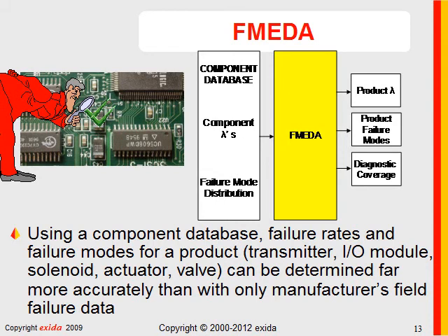But if, for example, that capacitor failed short circuit, it would take out a power supply, probably take a current on a 2-wire transmitter to full scale, and we note the impact of every single component in a design. That's what I mean about taking thorough advantage of all the design knowledge available for a particular product.